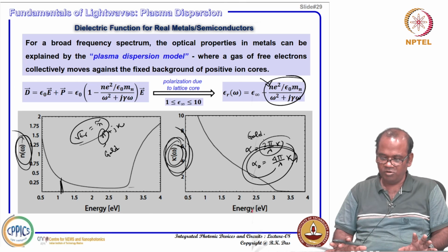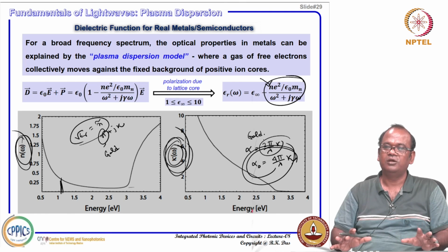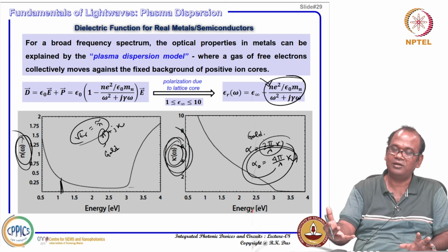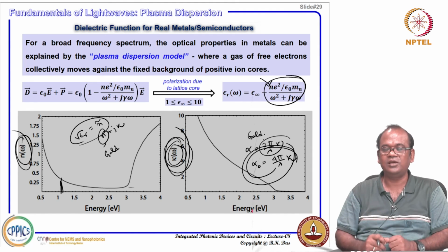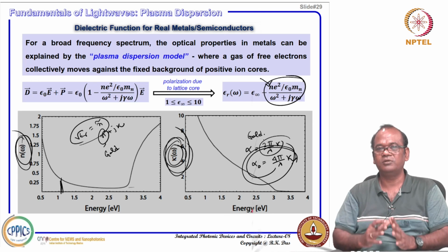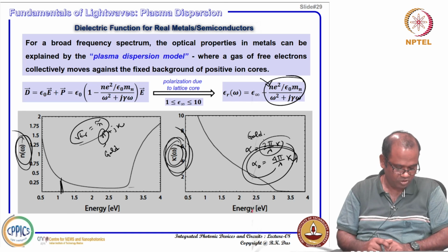So, it is very important when we discuss photonic integrated circuits, particularly modulators, where you convert an electrical signal into an optical signal. When you design a modulator, this is very important. You have to think about how to control the carrier, how to control the refractive index and how fast you can do that. That is how modulators are designed.